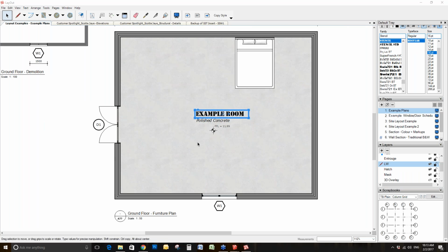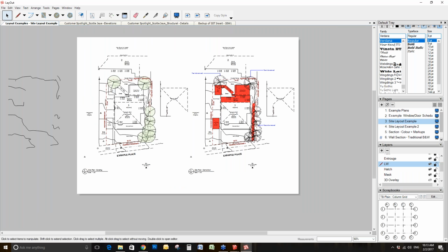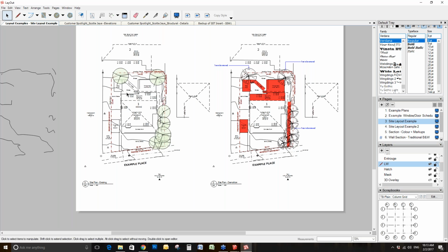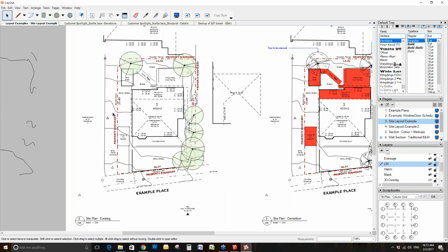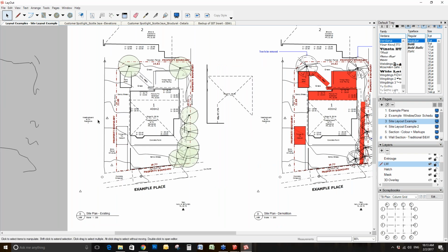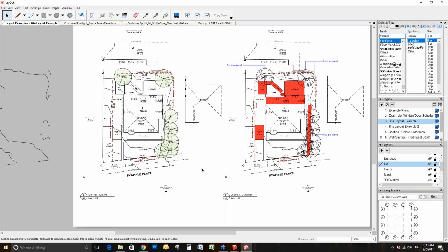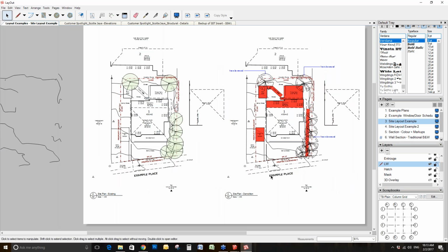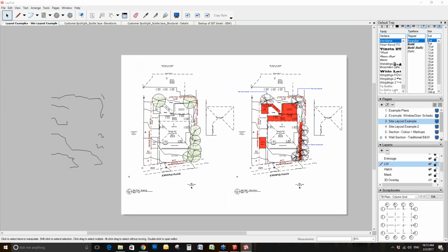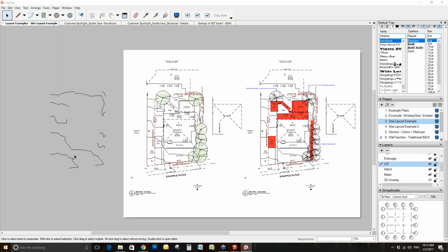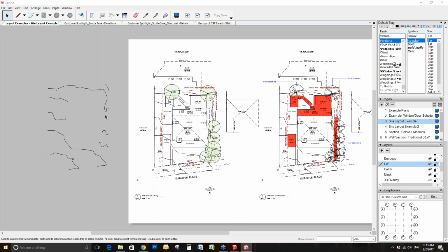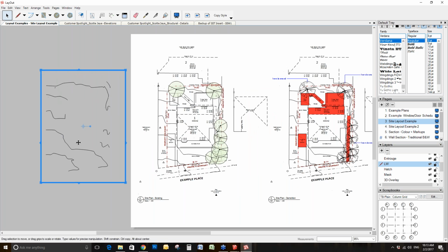There is something that's worth noting, and that is in your site plans. Yes, your symbols won't come through from your DWG format often. There's a problem with the way that SketchUp reads the DWG blocks sometimes. So maybe just try to explode your DWG, completely explode all your blocks, and then you should be able to bring in your symbols and even your text. But unfortunately, SketchUp doesn't read the text very well from DWG.